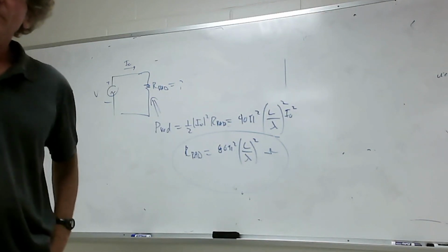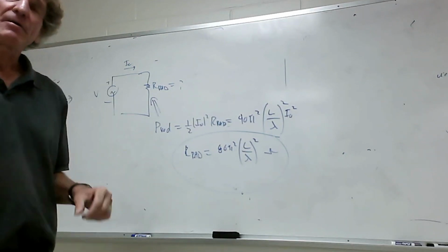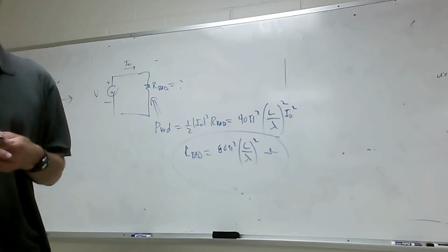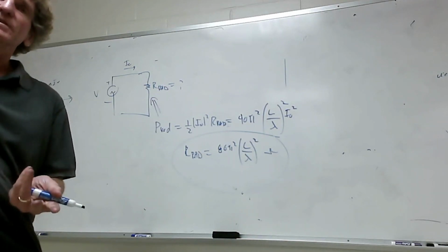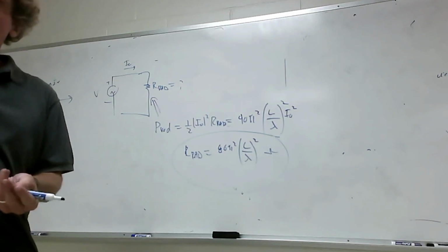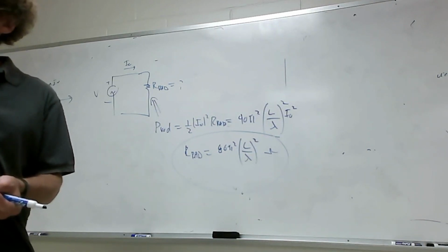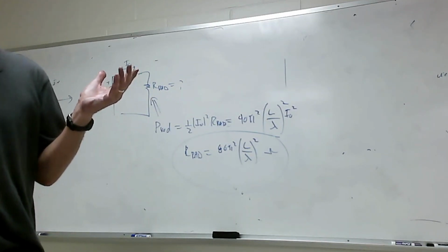Whenever you're running current through it, you're going to be dissipating power. That's why with these high power lines, you all have power lines, the whole idea is they like to transmit power with the highest possible voltage, so it'll be a minimal current, because power is voltage times current. Because any little bit of current causes a lot of loss. That's the reason they have such high voltages.